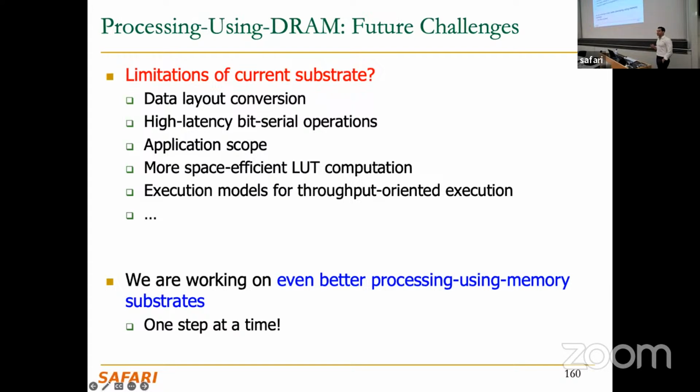This is not only true for processing-using-DRAM, and you might think, oh, this is an artifact of your own stupidity, that you created this problem in SIMDRAM and are just following up on it. It's not only SIMDRAM or MIMDRAM that follow this protocol, and it's not only DRAM-based processing-using-memory architectures. SRAM-based processing-using-memory architectures suffer from exactly the same problem, because they also need to transpose the data and operate in a bit-serial manner if they don't want to blow up the area with interconnect.